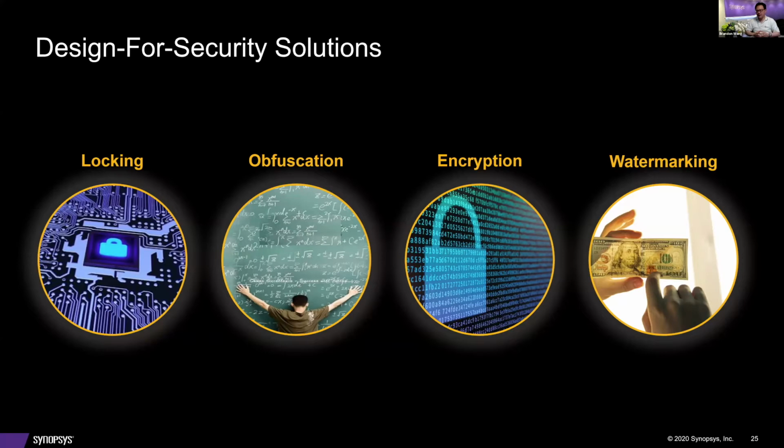And watermarking is latent circuitry that can be remotely triggered to produce a device authenticator. Such as sending a special string of bits would produce the watermark, which could then be used to validate the provenance.